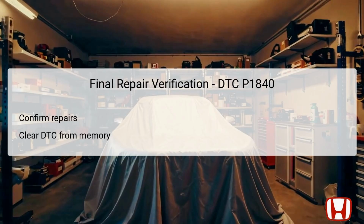After performing the necessary repairs or component replacements related to DTC P1840, the final repair verification is crucial to ensure the issues have been resolved effectively. This confirmation involves conducting a final inspection and possibly rerunning the earlier diagnostic procedures to determine if the system operates normally post-repair. Technicians should then use the Honda Diagnostic System, HDS, to clear the DTC from the vehicle's memory.